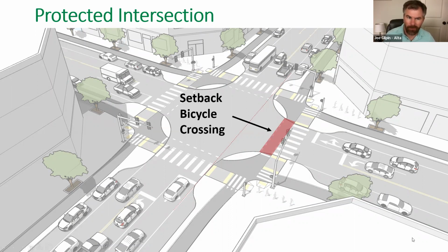So a lot of benefits in using this. The benefits translate also to pedestrians in a lot of cases. There's more pedestrian space, there's shorter pedestrian crossings. Depending on where you locate your push buttons and what type of accessibility features you install with the protected intersection, you could actually improve the efficiency of the intersection. And we learned last time when we talked about larger intersections, a lot of those are really controlled by how long it takes a pedestrian to get from one end to the other, because you have to have this very long clearance time to be able to get pedestrians across.